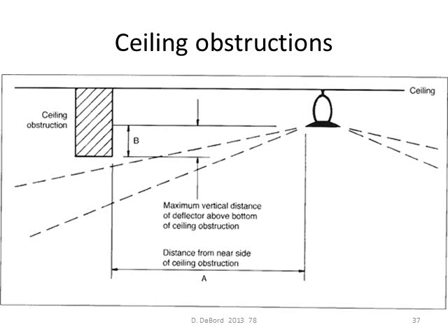In NFPA we have charts that show us the distances we can be, how far the sprinkler has to be away from the wall to get under it. If the sprinkler was right next to the wall, obviously it's going to be more of an obstruction than if it's 7 feet away from it and it's only 12 inches deep. We can easily spray under it.